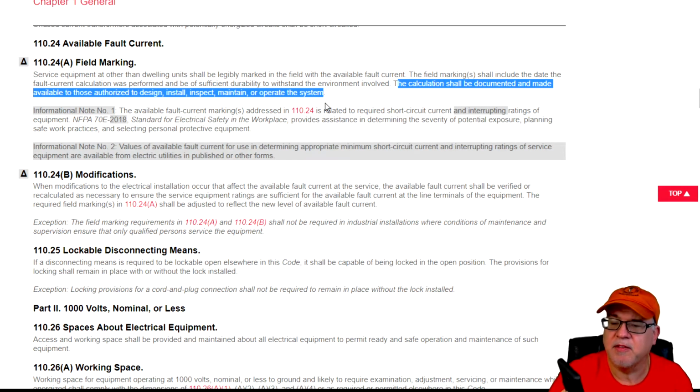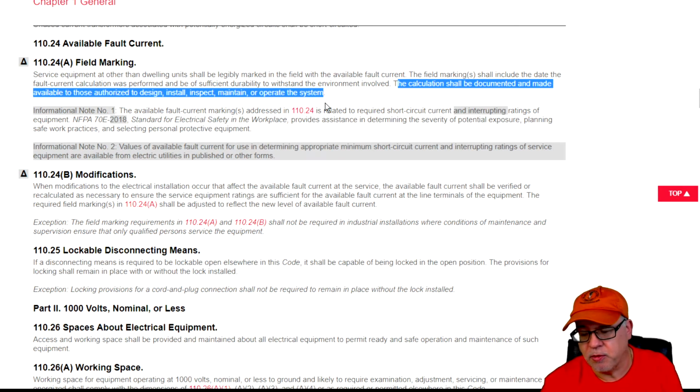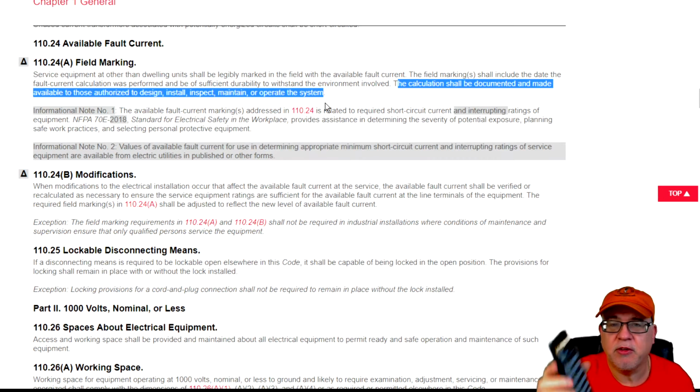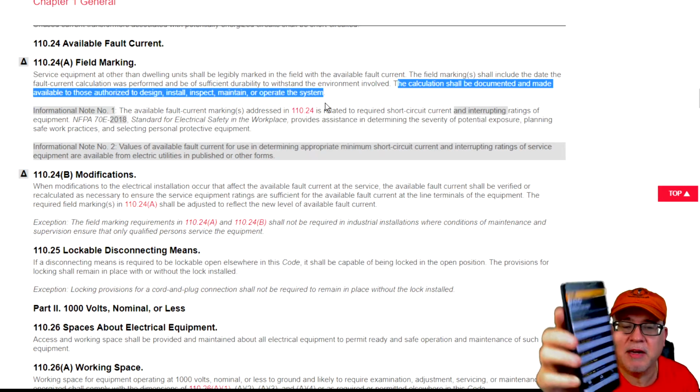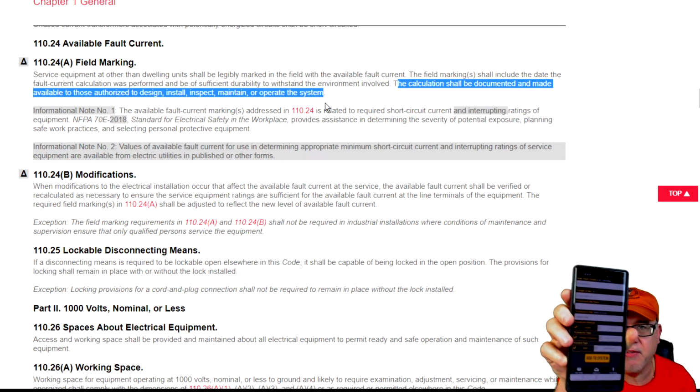You simply add to the system, and it says add a transformer to the system, and add conductor runs to the system. So if I already know the transformer's available fault current, then you see how the app will actually tell you. I could have shared this on the screen, but it wants to know what the available fault current is line to line, and this is usually going to be at the secondary of the transformer. And then you can put the voltage, you can put everything down here, and the length of the run, the number of conductors per phase, the conductor size, copper, aluminum, everything like that.